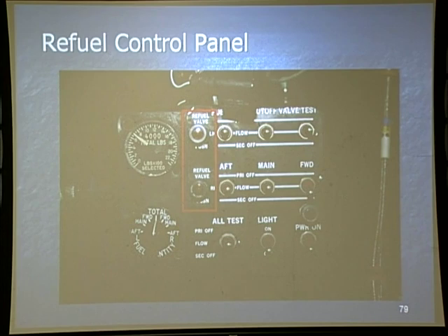But when will I be able to confirm it? During your fuel consumption check, during your cruise check, you're verifying that the fuel from the aft aux tank is transferring to the main. If that valve did not close, that fuel transference will not occur. And now we're what? That fuel is classified as unusable. That fuel is now classified as unusable, so now you're going to have to take it out of the fuel quantity system. Any questions about that?